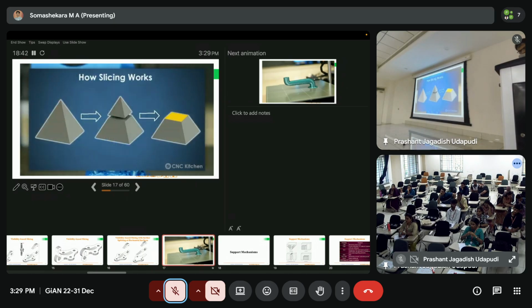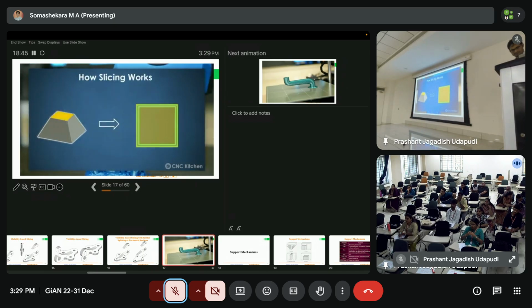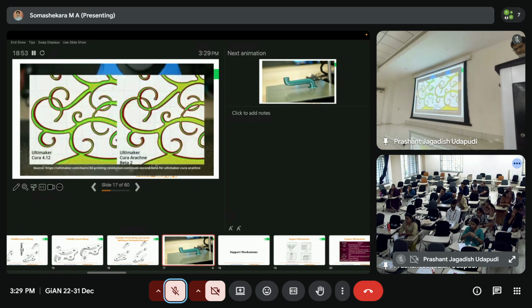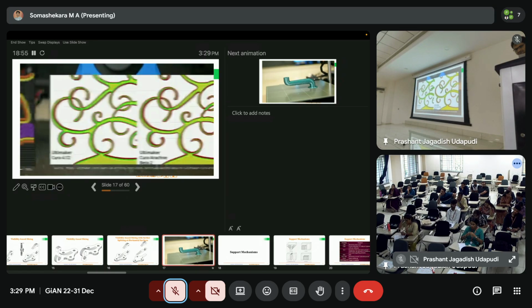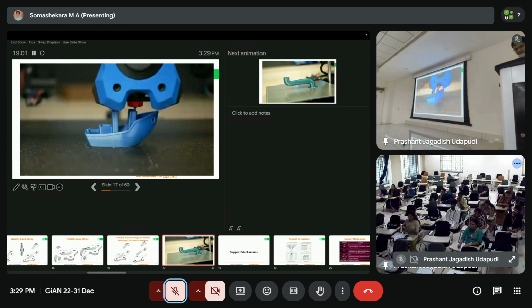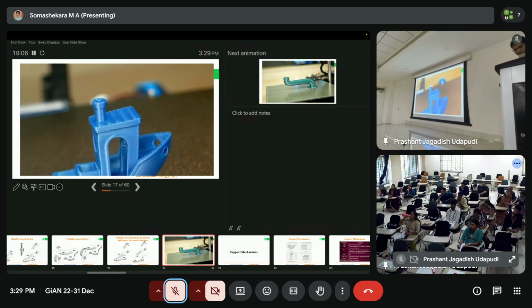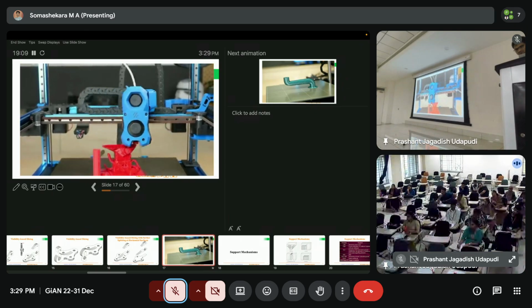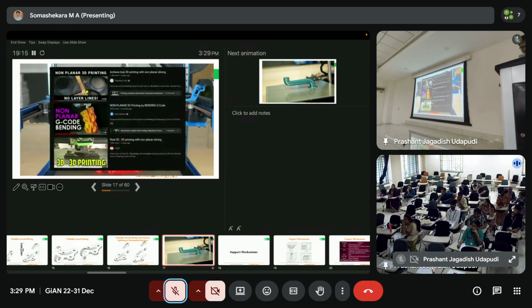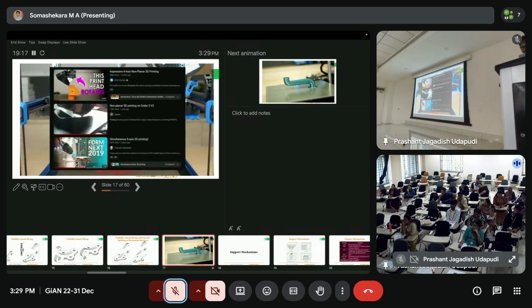Cut a three-dimensional part into a two-dimensional slice, draw the perimeters around the circumference, and fill the rest with one of many infill patterns. The only real evolution we've seen this year is the Arachne perimeter generator, first seen in Cura, that dynamically adjusts the width of the extrusion for more details and less gaps. Still, everything is on a two-dimensional plane, which causes the typical stair-stepping patterns on sloped surfaces and, of course, requires supports on overhanging structures. Over the years, we have seen a couple of approaches of non-planar slicing, often to improve top surfaces, yet none of them ever really made it into a mainstream slicer.